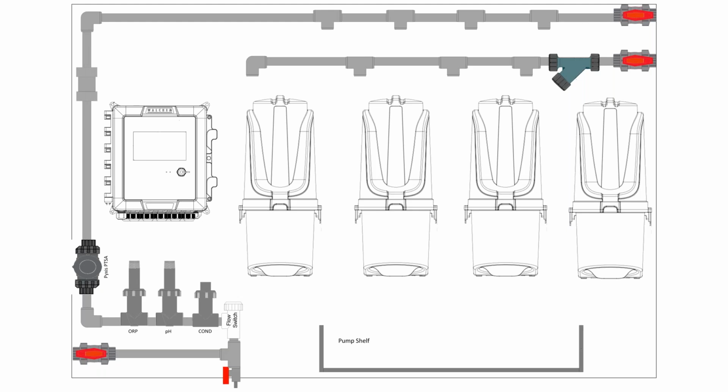A beautiful thing about solid chemistry is we have supplemental products to help boost chemistry fast. So all of our scale and corrosion inhibitors come in stick form, so you could manually slug dose the system very safely and very quickly to achieve product boosts in short order. So instead of taking a liquid formulation, either running the pump for 10 hours or 4 hours or 3 hours, or trying to figure out a way to transfer a product into a container that then transfer into the system, our supplemental products are really nice for that.